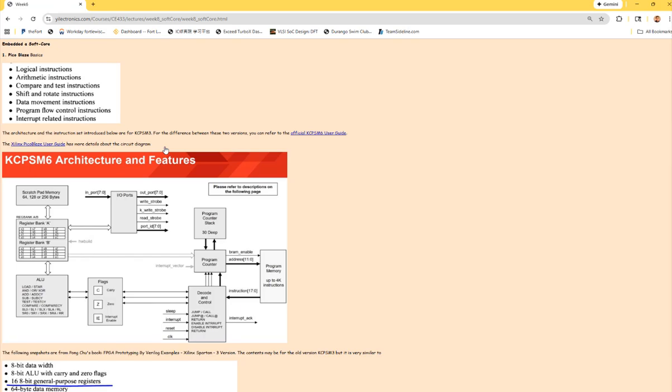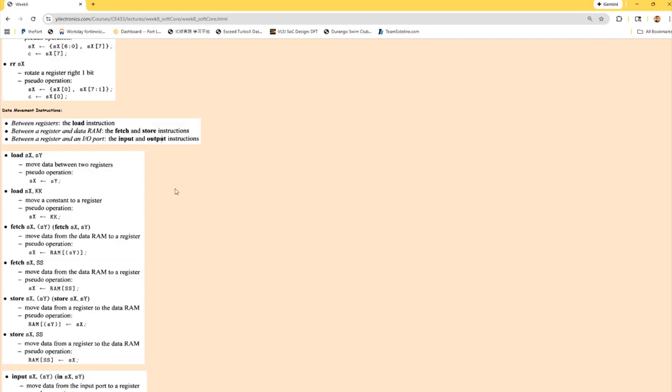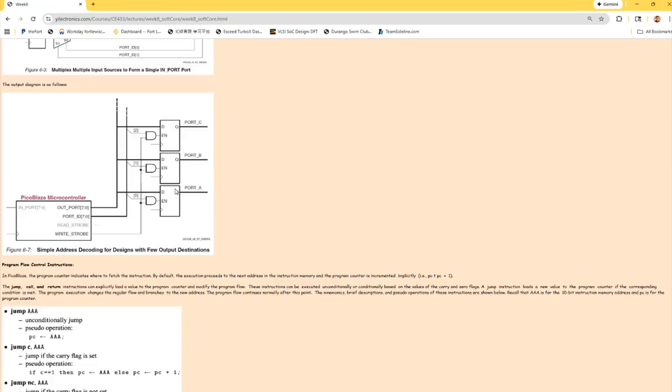A hard core is when a digital designer designs an FPGA chip, they optimize everything. They probably even manually adjust a lot of circuits in there, and they design their circuits with all the LUTs, and send it out for fabrication. So this is a soft core because we have the RTL. We synthesize it using Vivado, and we are able to program it using assembly.